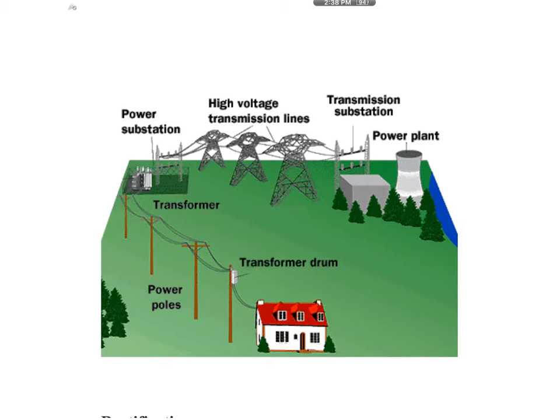So this type of power station that runs on steam must be operating continuously, because stopping and then starting again takes too long. The one that uses the exhaust gases to turn the turbine is very fast. That one you can operate in 1-2 hours. So for those power stations that need to operate very quickly, you use exhaust gases, but it's very wasteful. So you only use it when there is no choice, when there is a sudden spike in demand and you cannot meet it, then you quickly turn this kind of power station on.